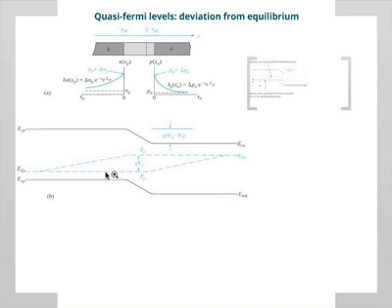It doesn't really change much. The electron Fermi level actually starts going up because there are more electrons there. I exaggerated this obviously, right? You can see. Then on the other side, the opposite happens and the two Fermi levels do meet. Okay? And the difference between them is the applied voltage. This is forward bias. And of course, in reverse bias, the opposite thing happens.